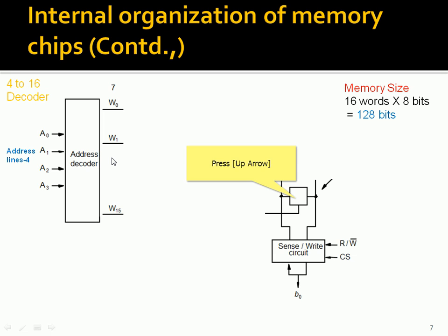In such a case, for a huge memory we need to use several chips. When several chips are involved in a big memory, a chip select signal will be released from the processor. To read some information, a read control signal will be released from the processor.